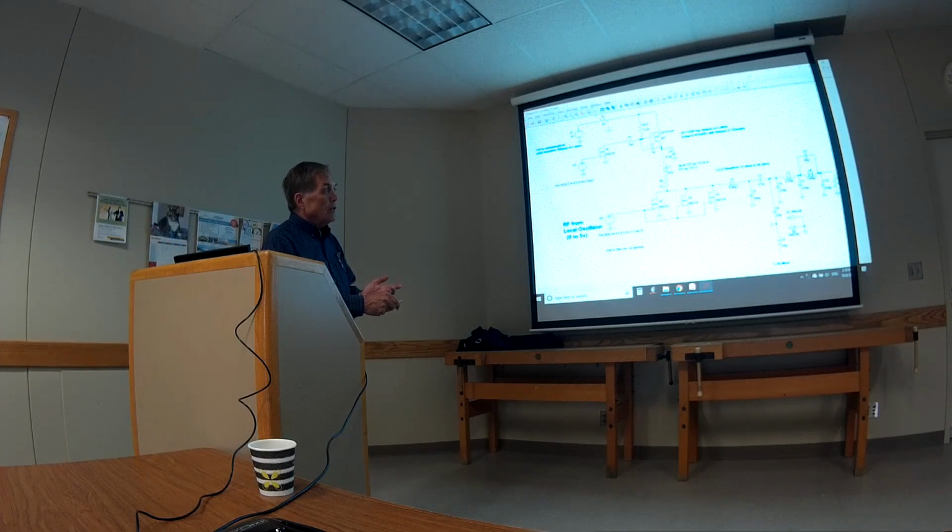And you can still measure the output here with this capacitive added to this one because these are in parallel. And this is just a little simple keying mechanism. I'm going to put a pulse here at a frequency that'll simulate setting that key up and down. And that's going to just key one transistor, a MOSFET, which is going to key the rest of this.